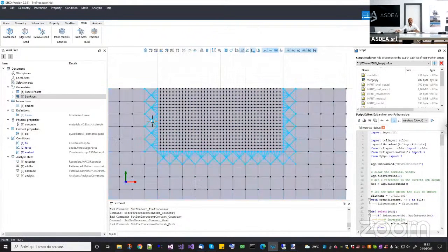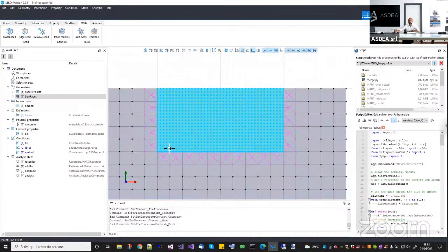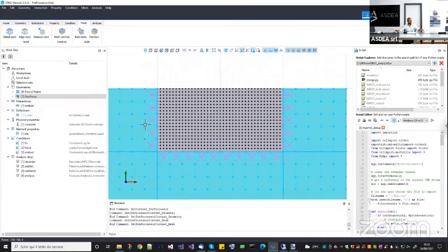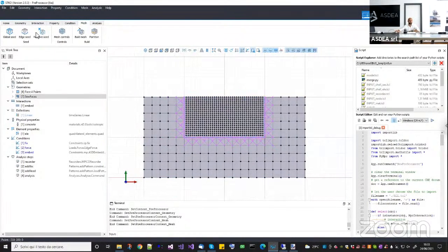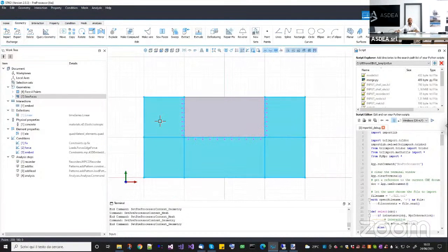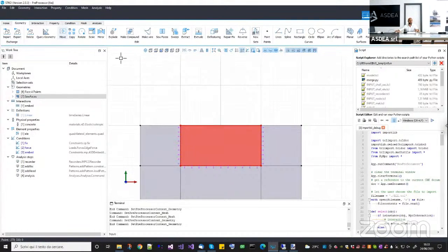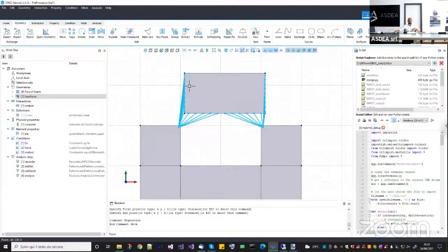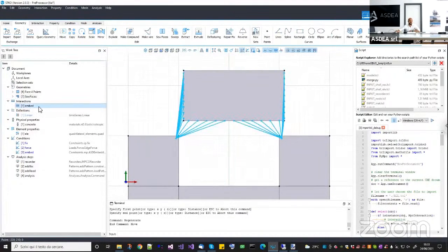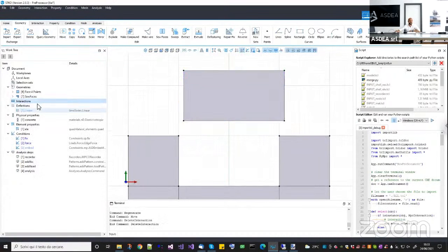The problem is that if you don't have any constraint, these two bodies will be separated. But if you attach them together, you cannot have this kind of mesh. You will have a kind of transition, so you will waste a lot of time because you have extra elements that you don't need. Now with this kind of approach, instead, it is pretty easy. You can draw your geometry outside, then the geometry inside. Then let me just move this one. I will show you how it works. Then you create an embedding, and actually I'm going to remove it and create it again.